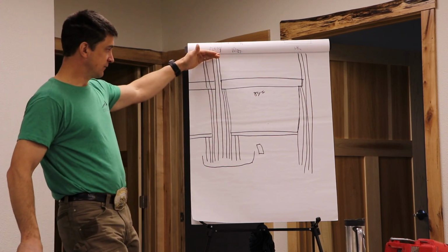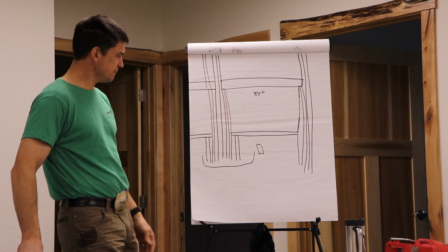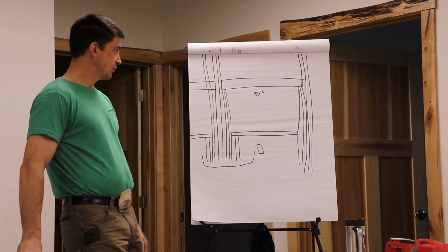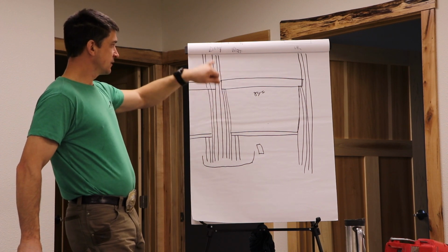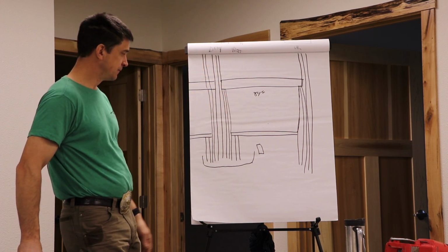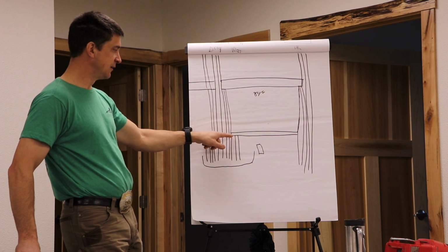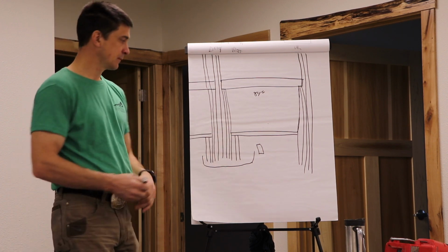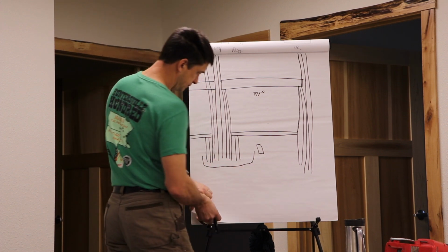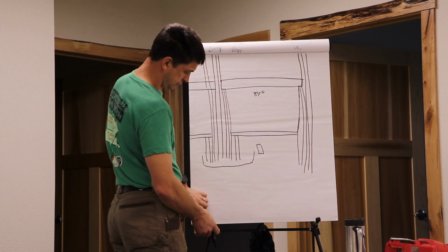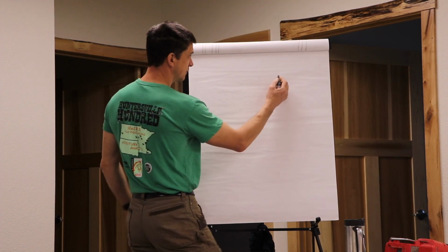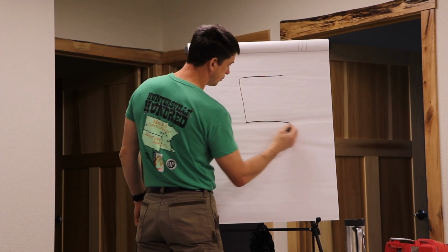But if this is an 8-foot tall wall, then let's just put in the framing that we need, which would be 1 king stud, 2 shoulders, and we don't have to have a stud at the end of a sill plate. Okay? When you're framing for a window, okay, here's your window opening.